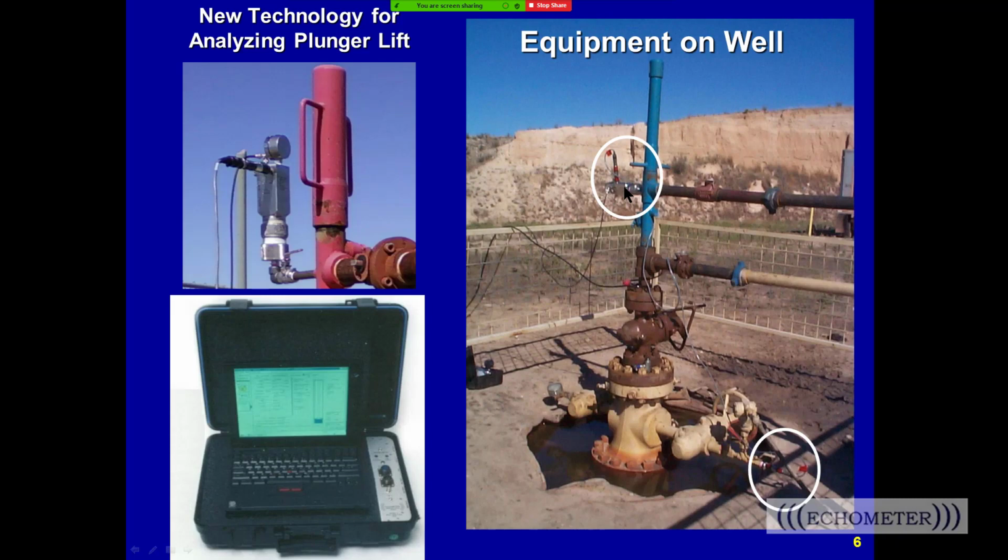That would take some time, and often it would extend the shut-in time, and that would cause the plunger to have extra casing pressure, and the plunger would come up somewhat dry, often dry and too fast. And I'd wonder why would the operator operate the plunger like that, until I realized it wasn't the operator, it was me, the way I was installing the gun.